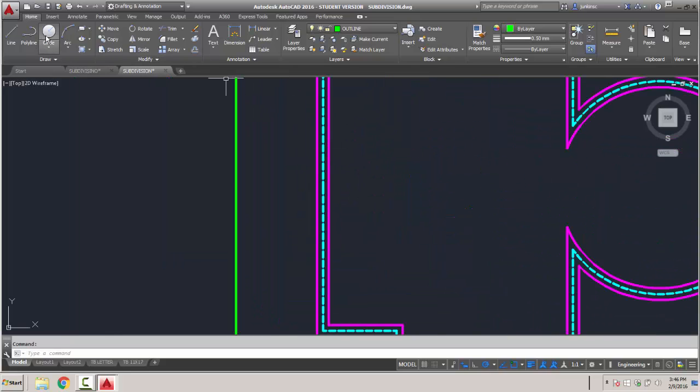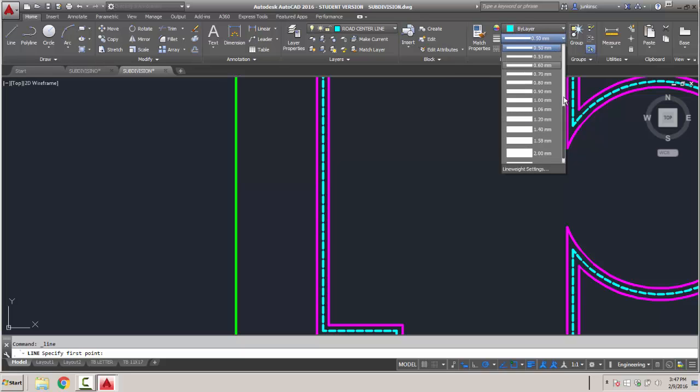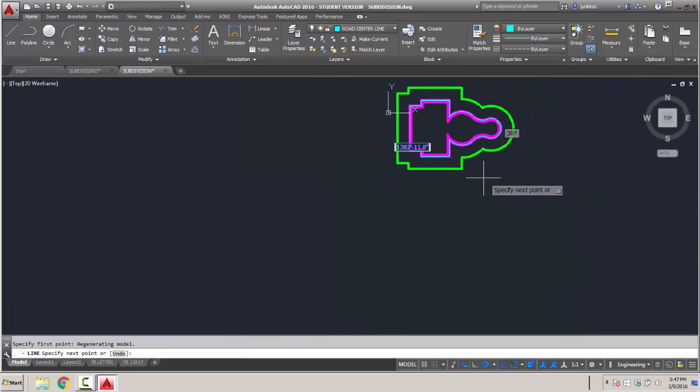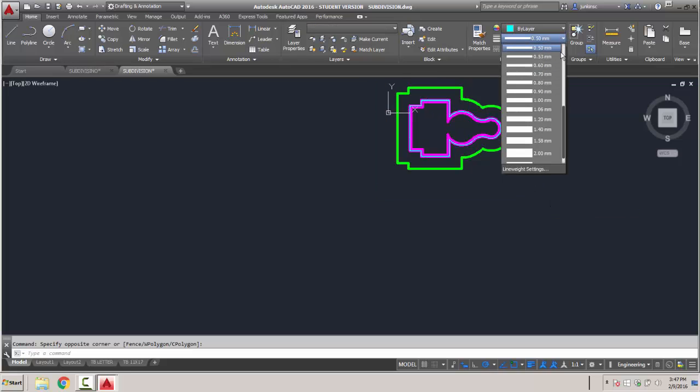So now we're going to take our center line option, road center line. Oh, that's why. This should all be by layer. Why was that set that way? So let me just select everything. This should be by layer.